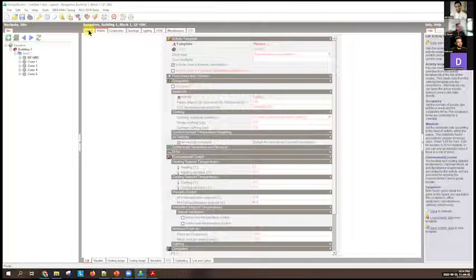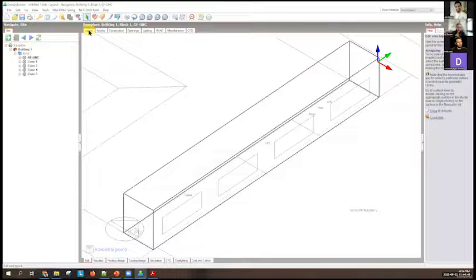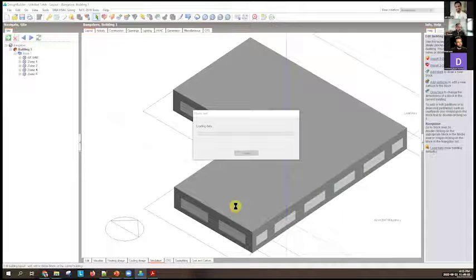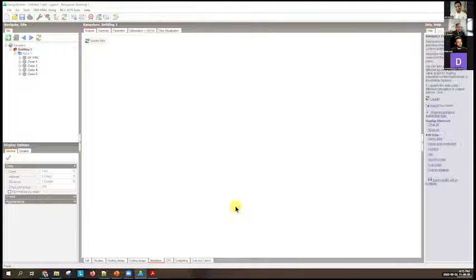At this point, I don't know anything about construction, I don't know about the glazing, I don't know how the building operates. We'll check all of those out. But I want to just do an energy simulation so you can start exploring the software. So I'm back at the building level up here. I'll go to the simulation tab, and then I will choose to run a simulation.